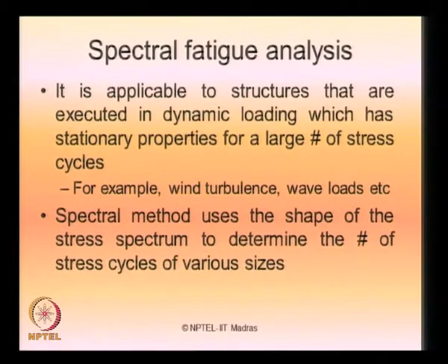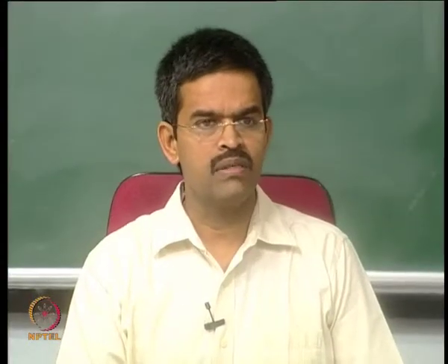The spectral method uses the shape of the stress spectrum to determine the number of stress cycles of various sizes, because in the last example, the rain flow counting method, the shape of the stress spectrum was not counted. We only look at the peaks and valleys of the stress cycle and counted the number of cycles in the stress range, and found out the fatigue damage estimates.